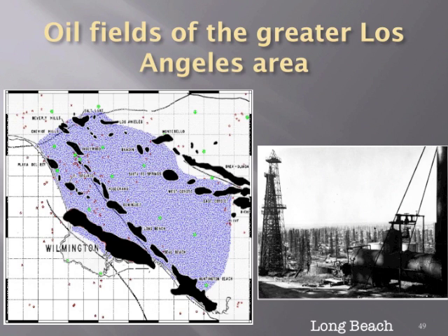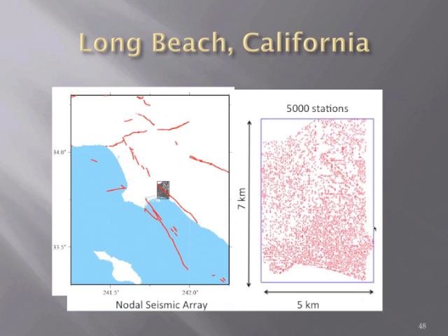I think we have 3 months of data. So we did 3 months of data cross correlation. Actually, the data is huge because when we originally got the data it was 250 samples per second. So the whole Long Beach array data we got is larger than the whole IRIS data set. And we actually needed to decimate it quite a bit in order to process it. Otherwise, it would just take forever.